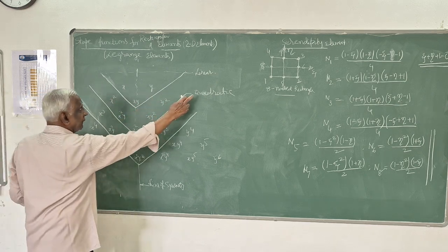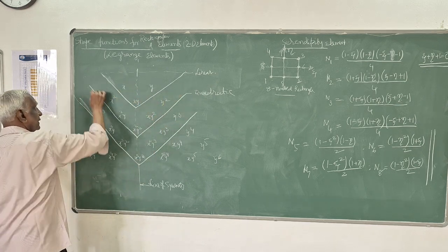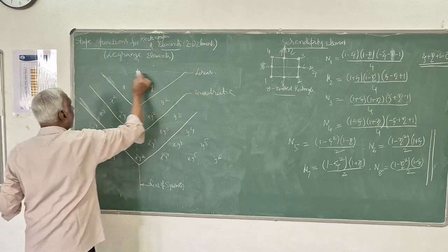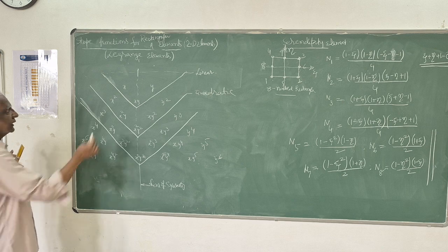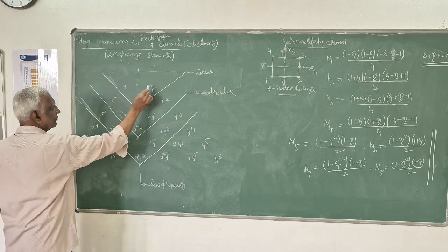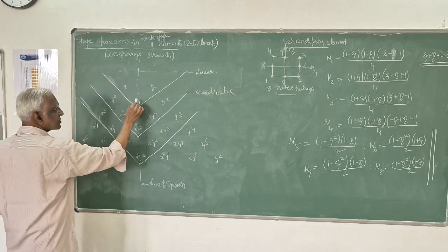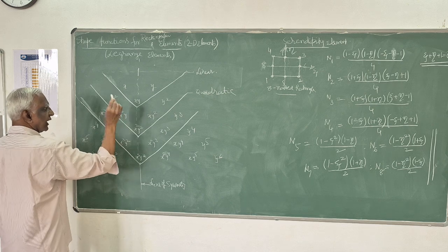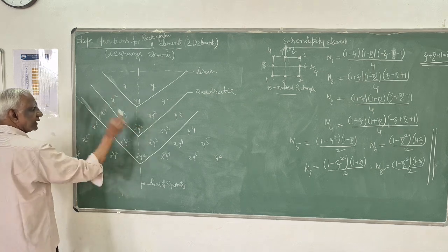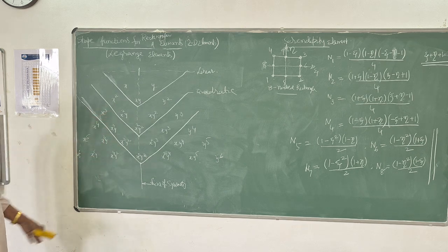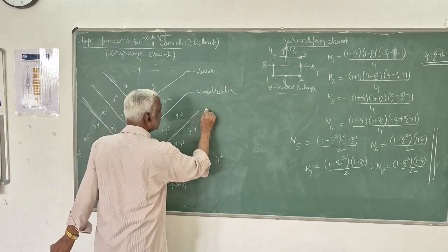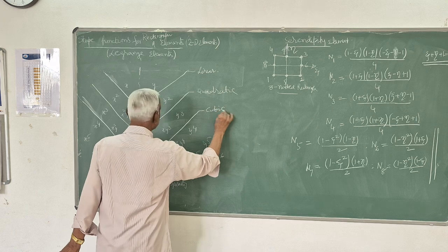In quadratic element equations, you will find this second triangle. All the terms in this second triangle, that is 1, x, y, x square, xy, y square, x square y, x y square, x square y square, are found. So that is for the quadratic element, and this is for the cubic element.